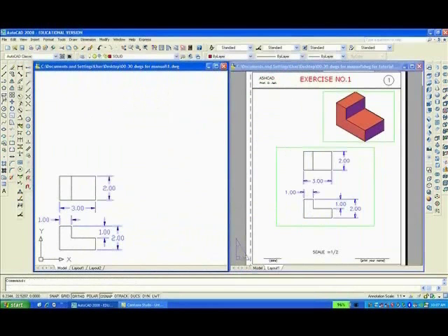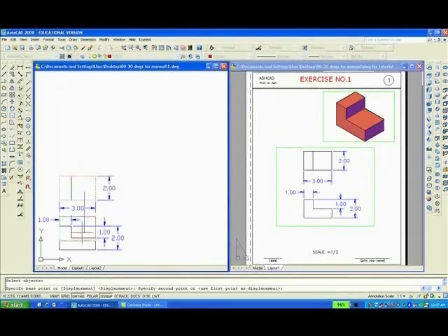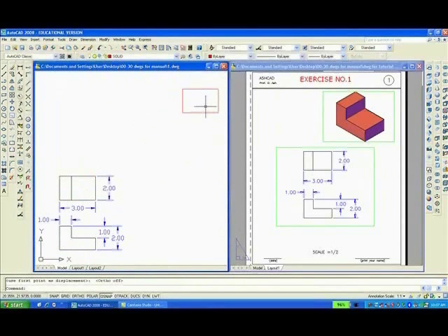Next, you'll want to go to rectangle command and pick 2 diagonal points. Then M, enter, L, enter. In other words, move the last thing you drew and move it up. Click ortho to take it off, put it in the upper right corner. Hit enter to repeat the command.